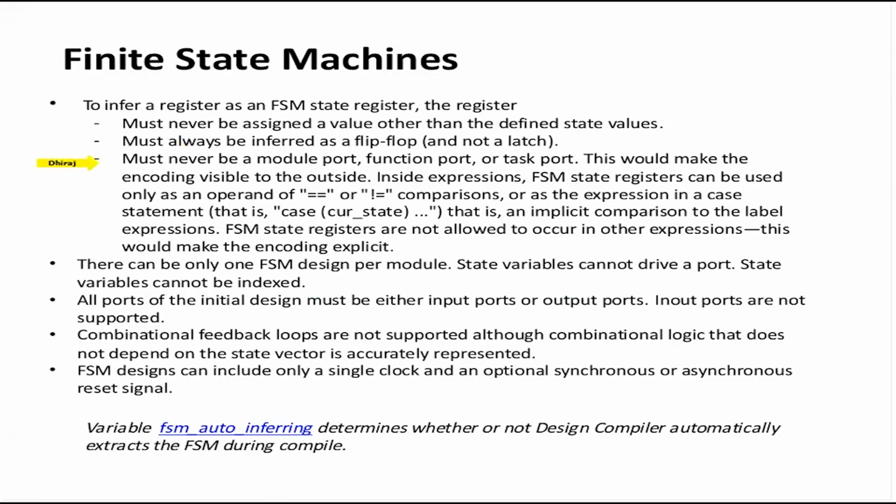The FSM register, all these are register rules, must never be a module port, function port, or task port. We are specifically talking about the register that maintains the state. It cannot be a port of any module, function, or task. It can only use operands like equal to or not equal to, that is, comparisons, and not any other expressions, since states will only be compared and no data operation is done on them.